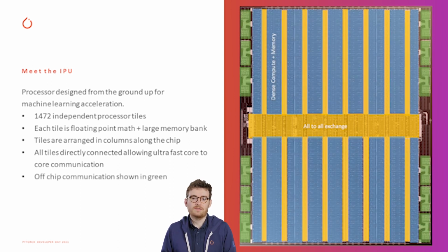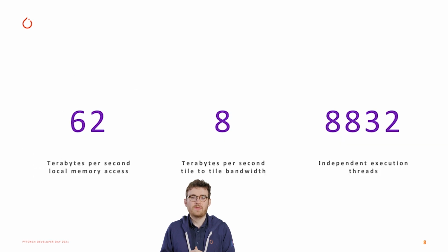These core-to-core connections give us high energy efficiency and lightning-fast bandwidth by having the compiler calculate the synchronization and communication logic and embed it directly into the final binary. This gives the IPU this incredible on-chip bandwidth, coupled with huge compute potential, since 100% of the chip silicon is dedicated to just machine learning.